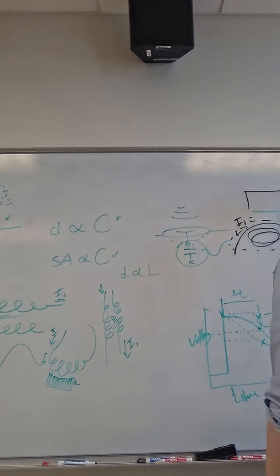And when there's the presence of a big block of metal, a big motor, big car chassis, a big scooter or whatever, then it couples to that. This big coil becomes a better inductor. Its inductance goes up due to the presence of the metal above it. And the system can see that change. It can detect that your car is there or not.